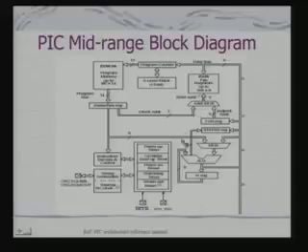This part is primarily the ALU part for doing arithmetic computations. And what is interesting, you will find that this RAM area is also being referred to as register file. Okay. In fact, all these RAM locations can be considered as registers. And as I have already stated, a RISC processor will have a large register bank, because it will use the registers for the majority of its operations. Here you will find that the same condition is being satisfied for the PIC processor.